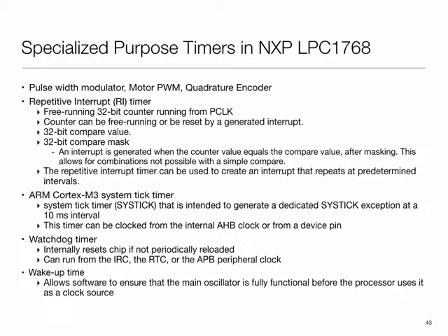So essentially, what happens is that you have an H-bridge structure, as they call it, where basically the time for which the power supply is connected to the ground is controlled by the transistors being on through these PWM signals, and therefore the longer duration they're on essentially is supplying more energy, and thereby I'm able to control the motor speed accordingly. So it gets used there.